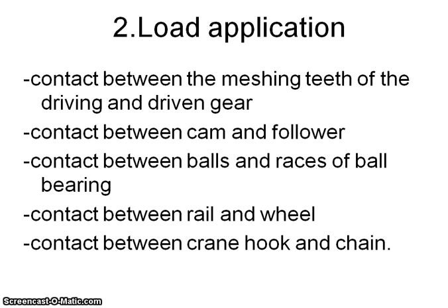So the pressure at that point is very excessive. For example, the contact between the meshing teeth of a driving and the driven gear, contact between the cam and the follower, contact between the balls and races of the ball bearings, contact between the rail and the wheel, contact between the crane hook and the chain. So in these applications there is a very large load acting on a very small area, and at that point the stress concentration will be higher.